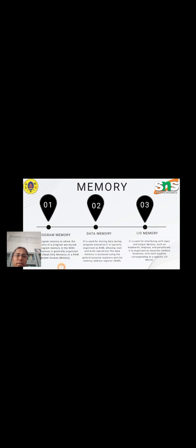Registers: general purpose registers are 8-bit, A, B, C, D, E, H, L. There are general purpose registers, temporary registers and special purpose registers. General purpose registers are A, B, C, D, E, H, L. Temporary registers are W and Z. Special purpose registers are the accumulator, flag register, instruction register. The 16-bit registers are the program counter and stack pointer.